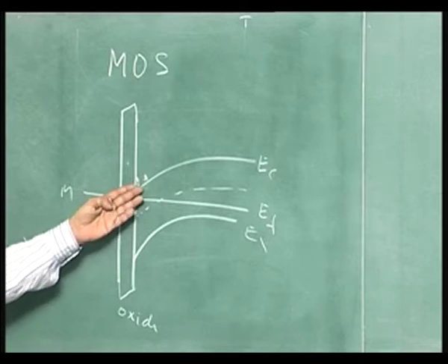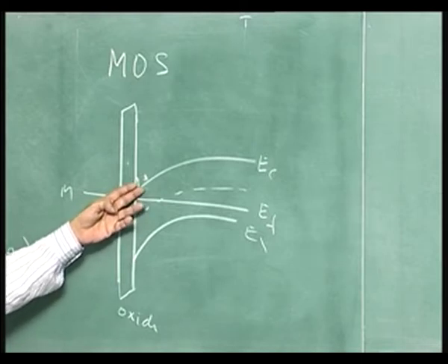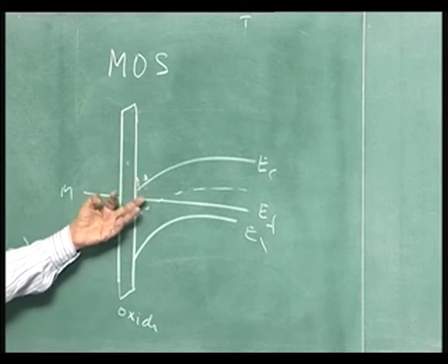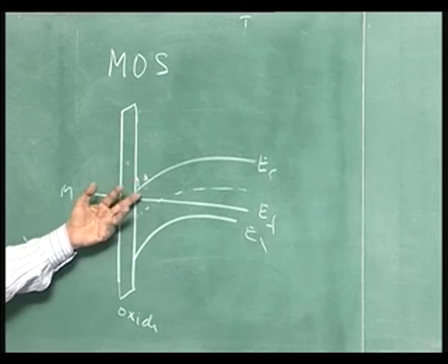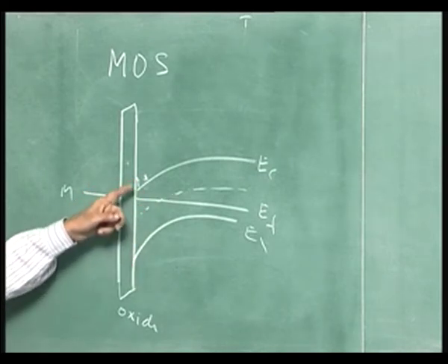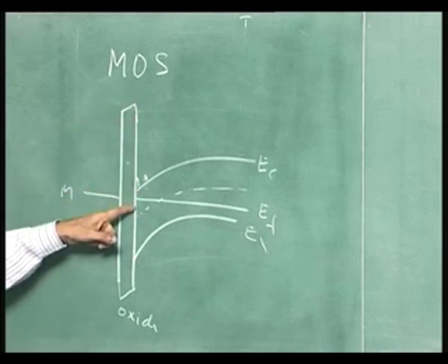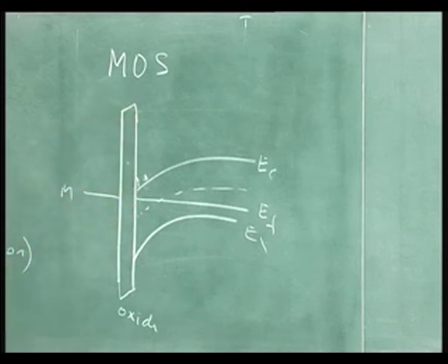The electron concentration may not be as high as you can get there, but you can go into the inversion region here, and they are locked up there because of this barrier. So, the same thing is occurring here. In fact, you can see one-to-one correspondence between the MOSFET and the HEMT.